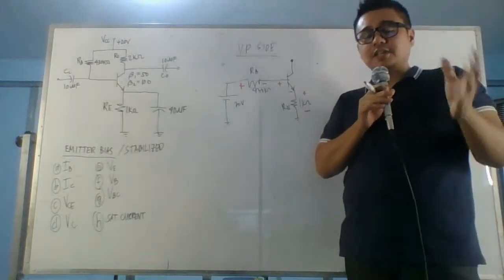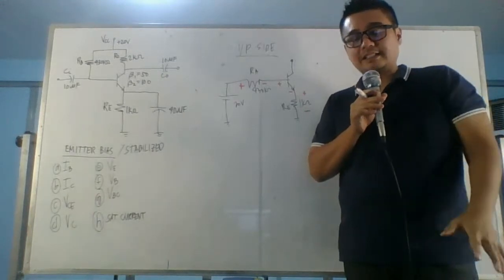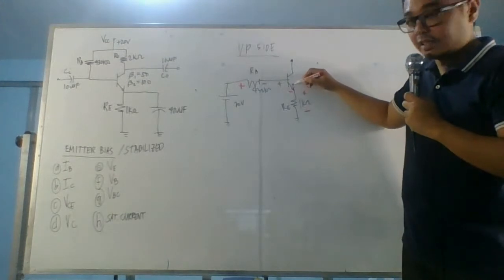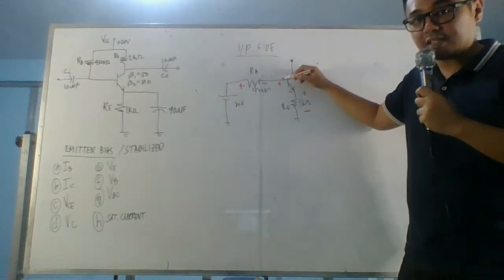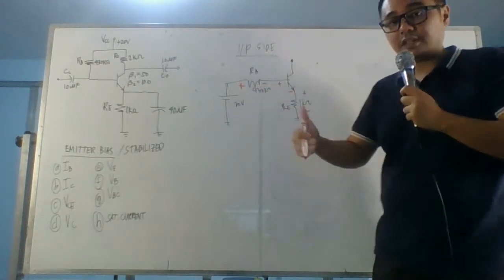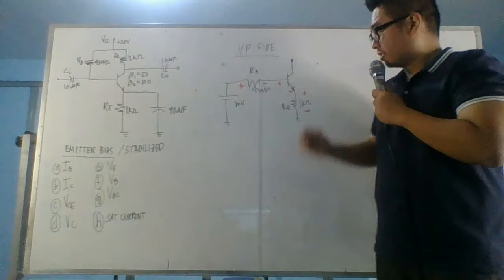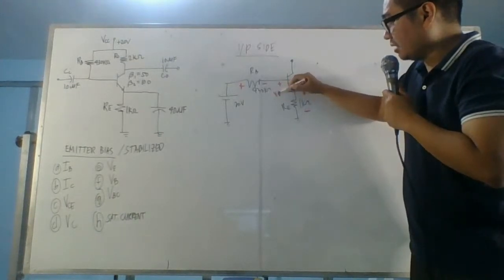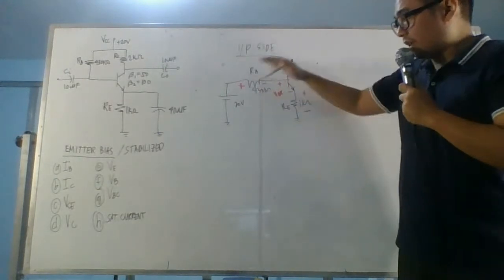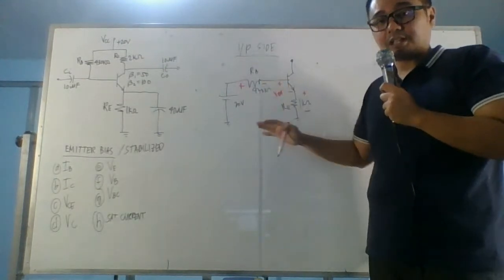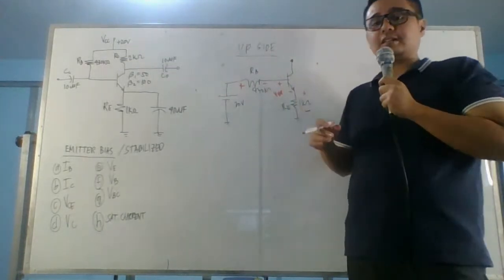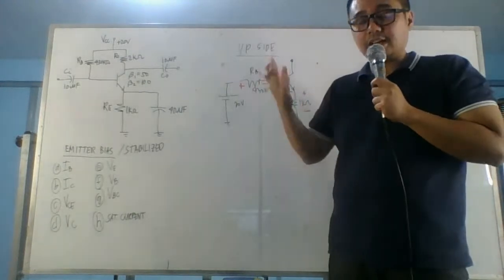Is the base emitter junction properly biased? This is NPN. So this is N-type, yung ating emitter. P-type yung ating base. So dapat yung P-type is positive and N-type is negative. So it is properly biased. So magkakaroon tayo ngayon dito ng VBE equals 0.7 volt. Okay. Ito na yung mga polarity. No, yun lang naman yung steps natin. No? Kailangan ma-master nyo yung steps natin kasi yun ang gagamitin natin. Lalo na hanggang sa dulo.